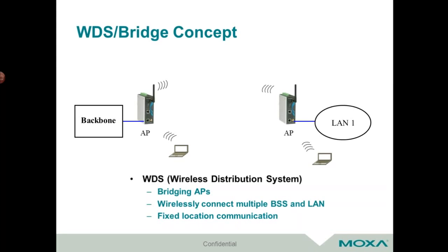But this type of topology is very, very useful when you're trying to bridge longer distances or bridge two separate facilities together. So say, for example, you have your control room, and then across, maybe an open field, you've got, I don't know, a water tank that you're trying to monitor with multiple sensors. You can wire all those up into a device that communicates to a wireless device. That will communicate back to your control center, and you have that dedicated link between the two of them.